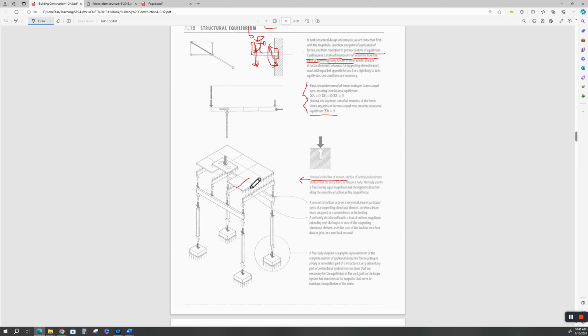Well, you got half of that uniform load going to this, half of this uniform load going to there, and half of this uniform load going to here. So that center beam has got to carry twice the uniform load that this one carries, right? Okay. So uniformly distributed loads, concentrated load,